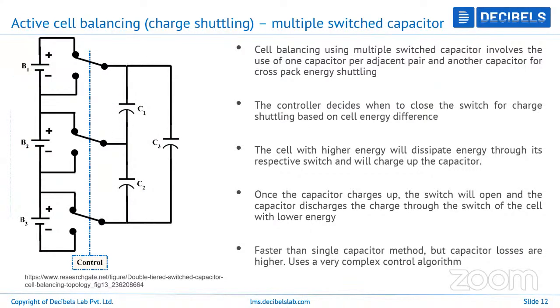But again, here it is a very complex control algorithm, because the states of the switches, and also the function and behavior of the capacitors, all three of the capacitors have to be monitored, right? So it's a much more complicated way of implementing this particular method. So this is a brief look at the multiple switched capacitor, right?